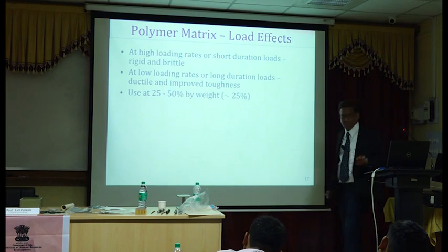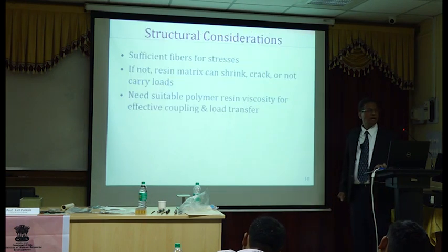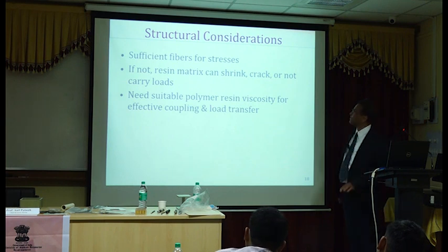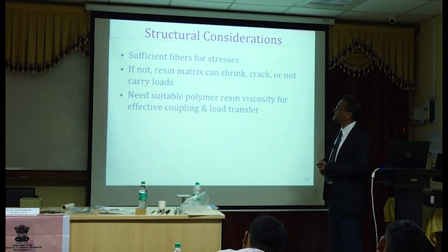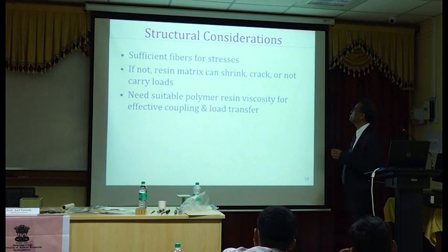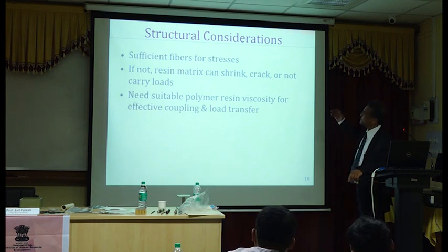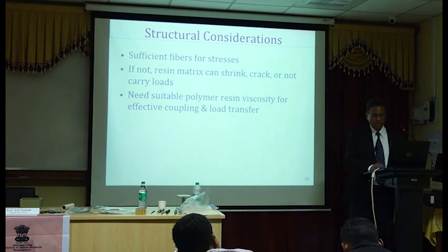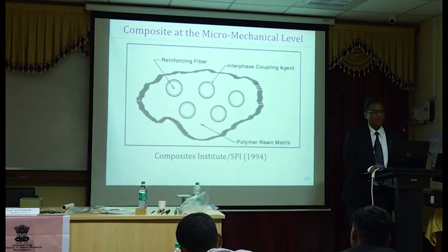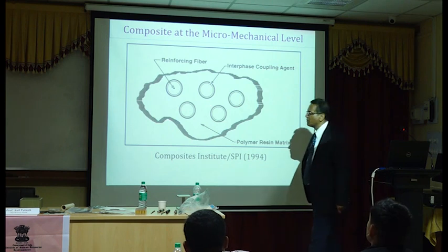Okay? All right. You should have sufficient fibers for stress consideration. That means the strength is always dictated by fiber in the fiber direction. And of course, you need proper viscosity for making sure the fiber is fully coated.